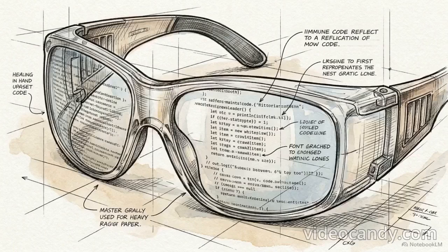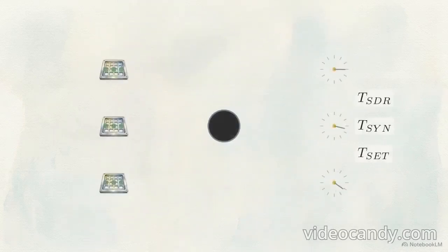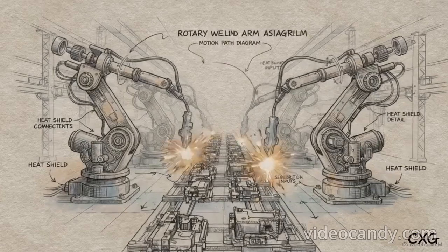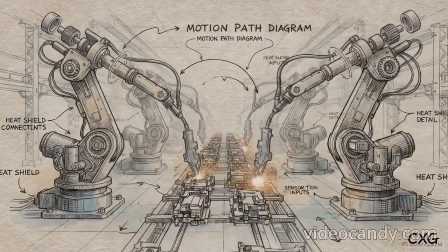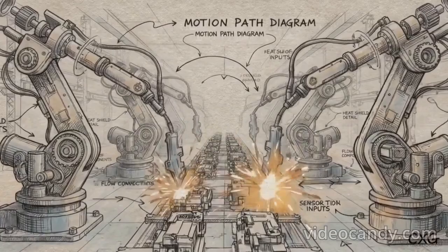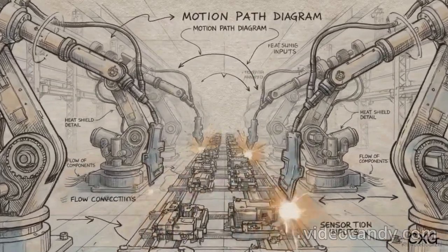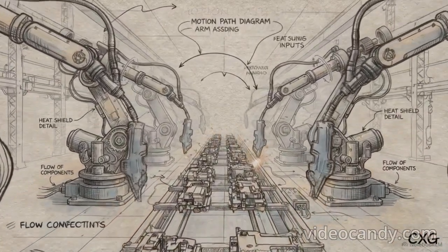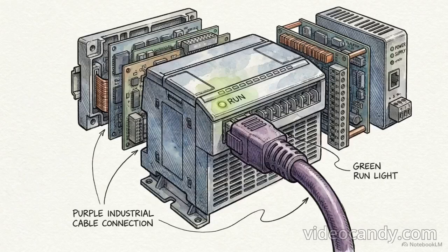physical station's capabilities. To resolve these handshake failures, we need to read the GSD architecture directly. We are going to deconstruct the file and isolate the precise memory mappings and timing parameters required for deterministic data exchange. Physical robustness cannot compensate for a broken digital identity. Mastering the ASCII GSD file is the absolute requirement for reliable interoperability on factory floors.